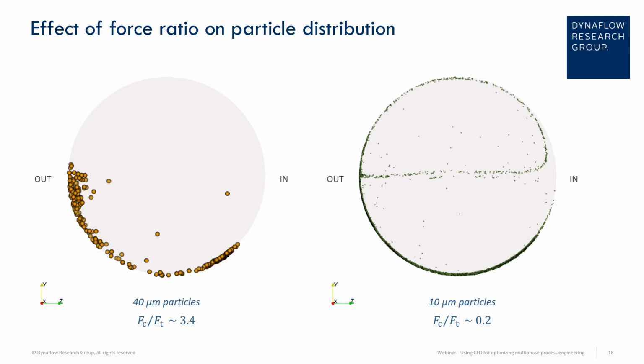Now, there are some notes that you could make here. If you look at the results for the 40 micron particles, since the centrifugal force pushes them outwards and they all cluster near the outer wall, that means that the distribution of particles will locally change the turbulence in the gas, and that there is a much higher probability of particle-to-particle interactions changing the individual particle trajectories. That is all true. So in that sense, this simulation, only considering flow-to-particle interactions, is quite coarse.